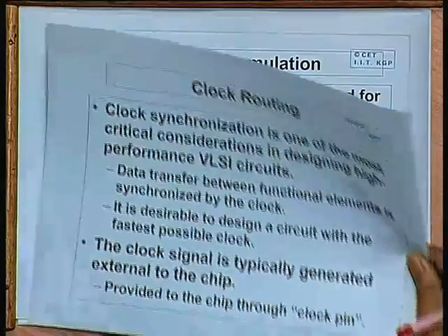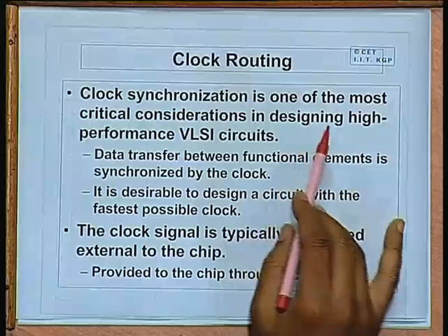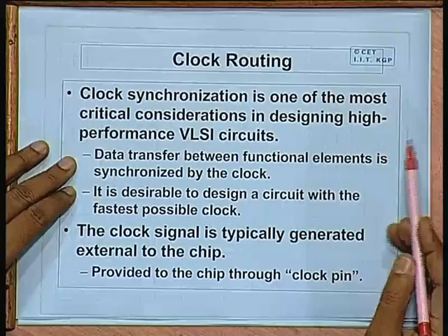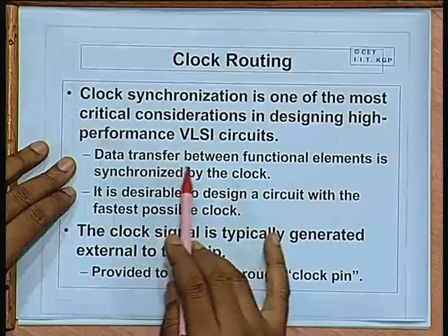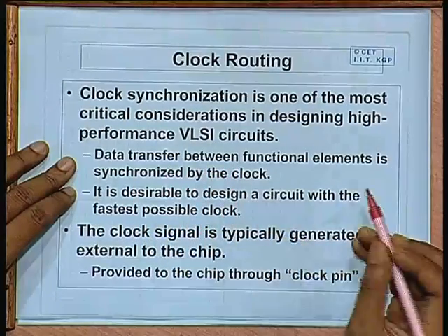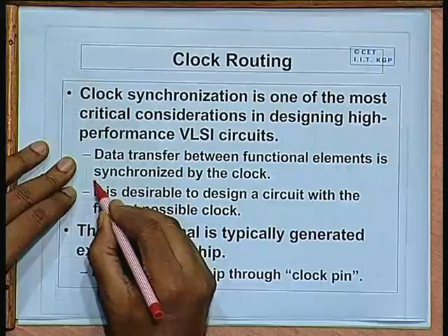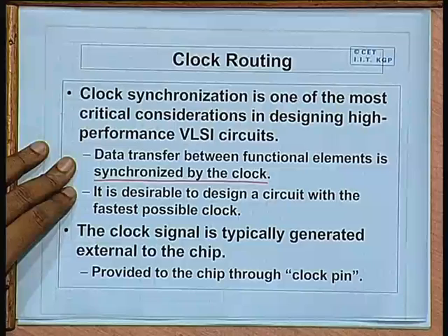Talking about clock routing, as you know, clock synchronization is very important in VLSI circuits, because in a typical VLSI circuit which works in a synchronous fashion, all the data transfer and operations in the data path are carried out in synchronism with the clock.